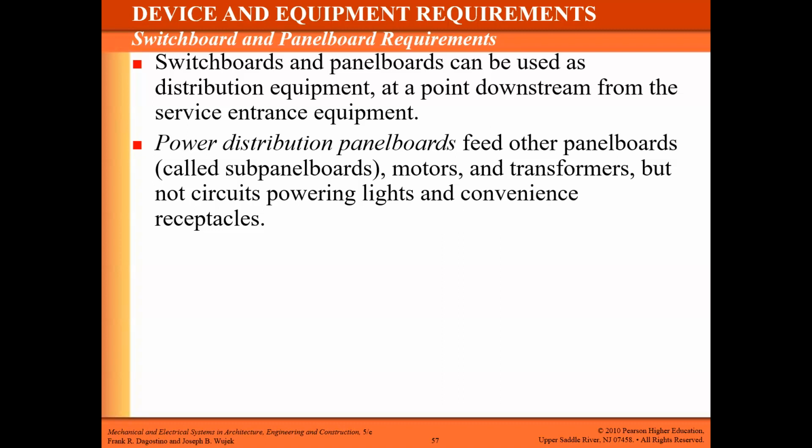A power distribution panel board feeds other panel boards called sub-panel boards, so you really can break this thing up into multiple pieces. As we had discussed previously, it sometimes makes sense to run a single cable over to a panel board rather than trying to extend all those little circuits really long distances throughout your building.